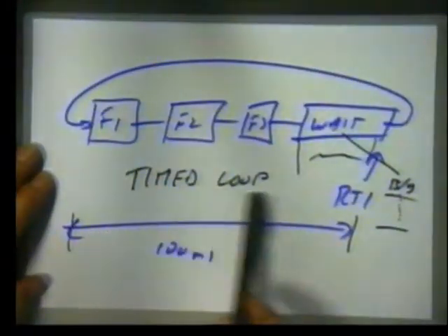Split your task down into the real-time events, the things that must happen, and they will be scheduled to run. Any time left over, get back to the background routine, do some housekeeping, update a printer, do a log, service a keyboard, all the things that are slow and unimportant. But then when the real-time interrupt comes around again, schedule these things to run. And you can do it under interrupt control. Take my simple timed loop, and now we can turn this into a multiprocessor function.